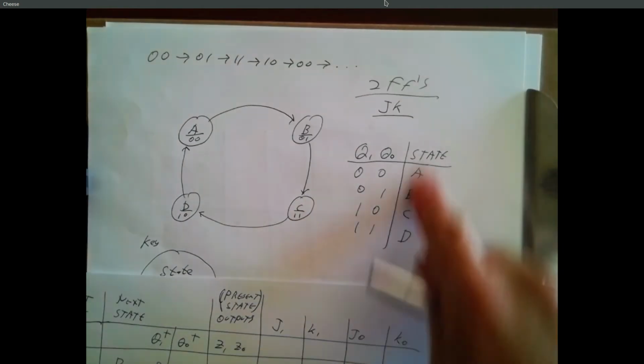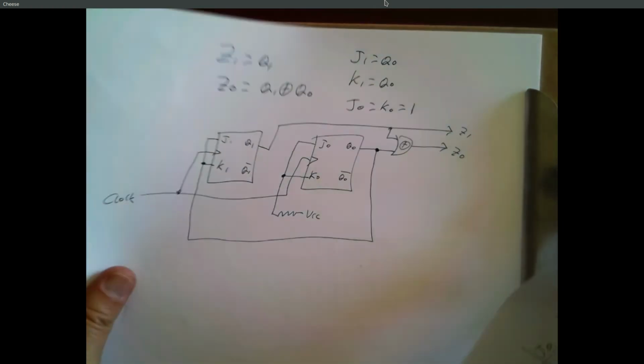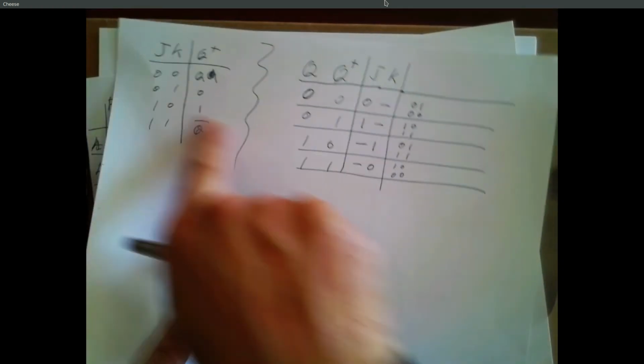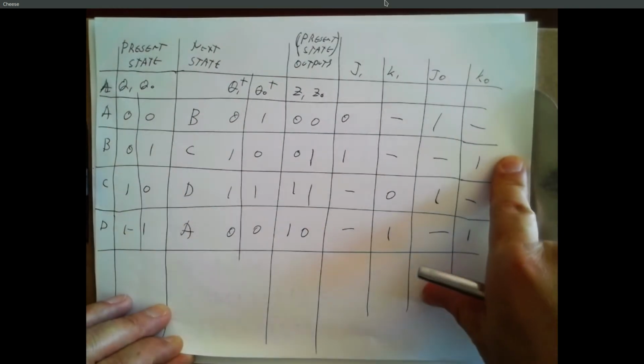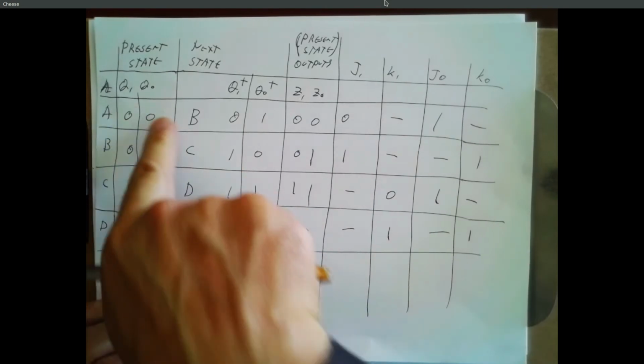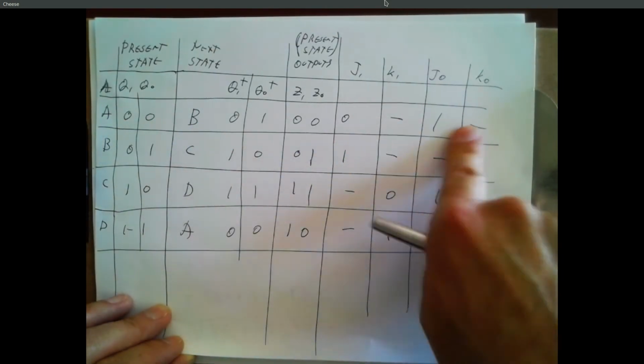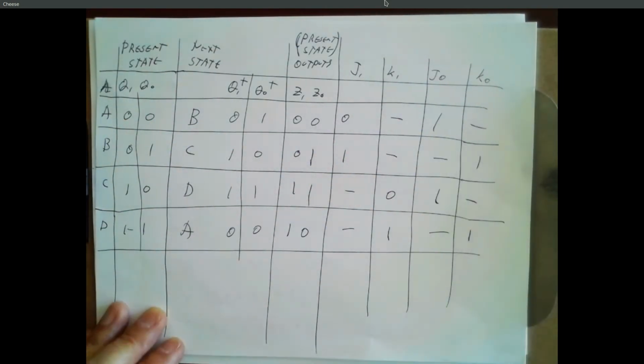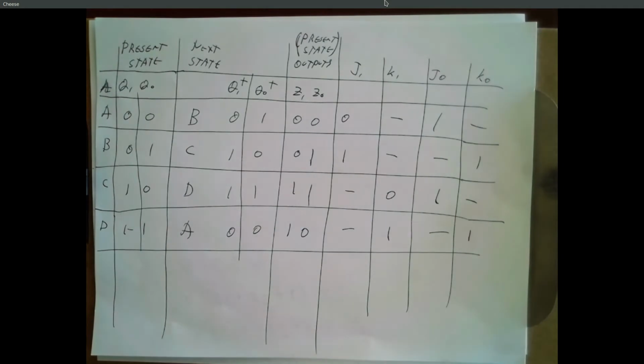So show your state table, and then when you're filling it in, it doesn't hurt to put down the table that you're using if you're filling in from a table. In case you've got a problem with that, I'd know where your errors come from. But then definitely show everything in the state transition table: present state, next state, outputs, and flip-flop inputs. So those 4 things. The circuit.